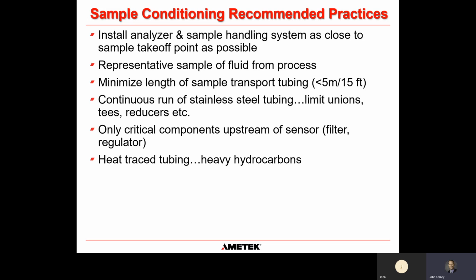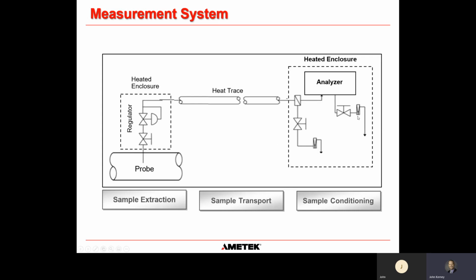I know there's a couple of questions that have come in on the chat. One is why do we recommend the sample rotometer and flow meter installation at the outlet side when it is a dew point analyzer system, and what if the flow meter is installed on the inlet side? Well, the reason I recommend a rotometer on the downstream side is most moisture analyzers don't need precise flow. They simply need just a flow indication. So it might be 2 to 20 standard cubic feet an hour or 1 to 5 liters per minute or whatever it is. But they just need some flow through them, and they don't need overly precise flow. So you're better off mounting a little rotometer downstream of the analyzer, primarily because it's more leak points and more surface area.